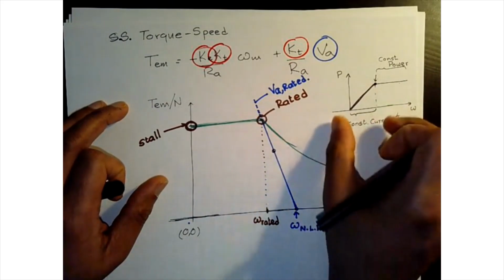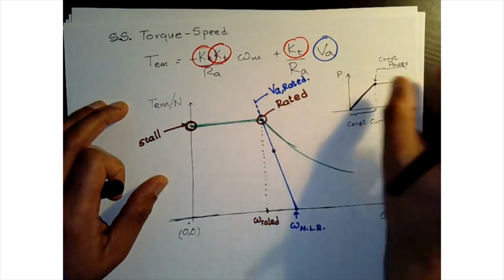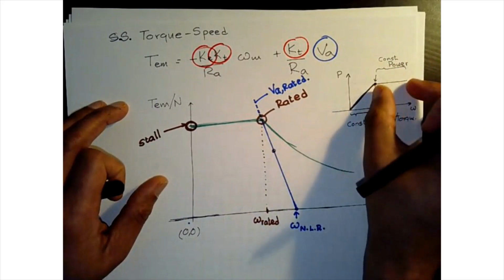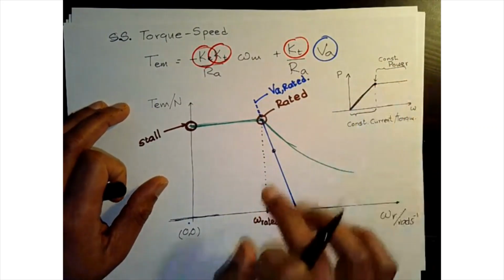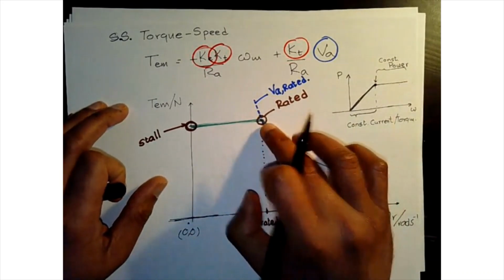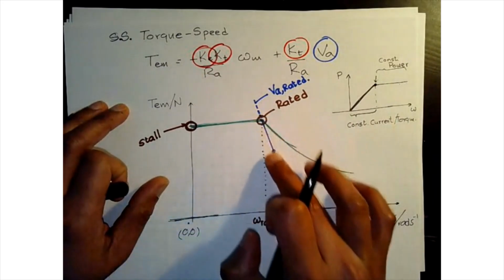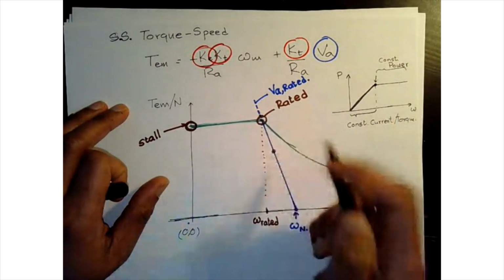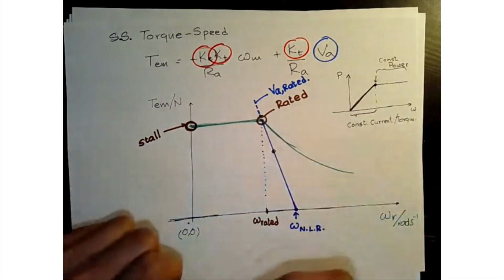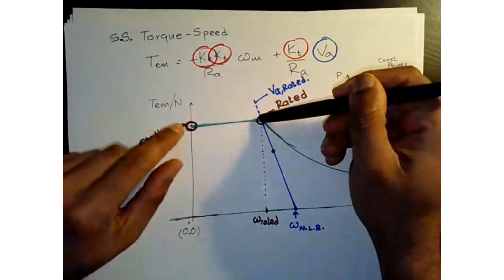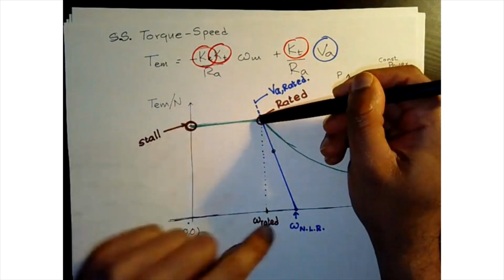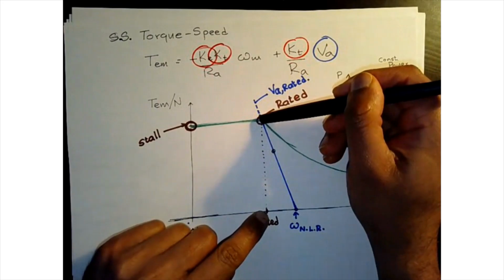So you can operate, and the key point is now you have a limitation in power for your system, right? You've reached your rated system, and now you can even move along here. You can move along, because you are at a maximum torque here and a maximum speed here.